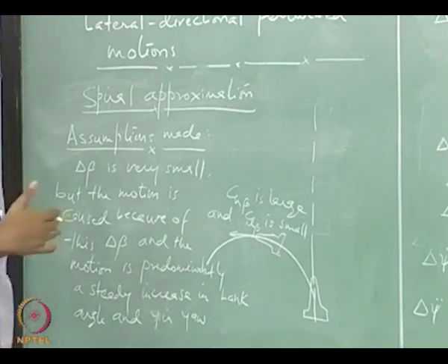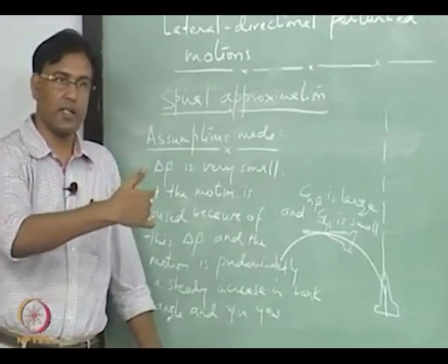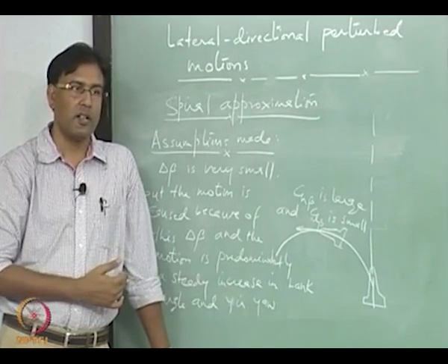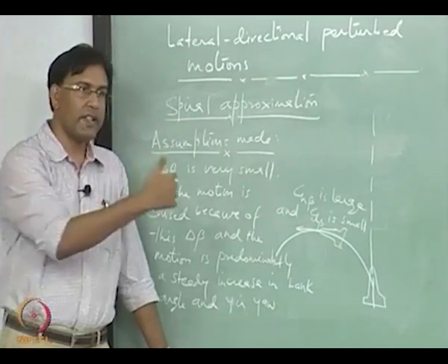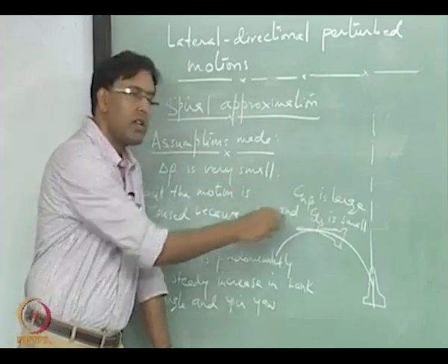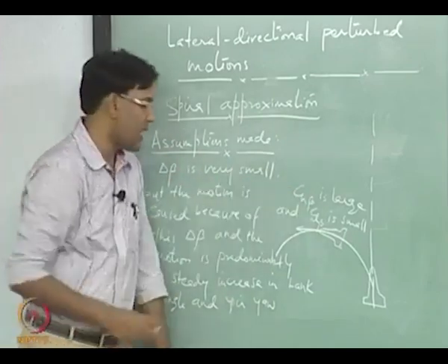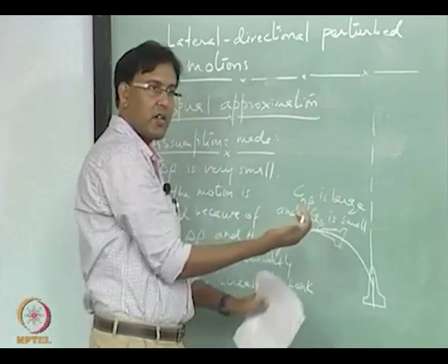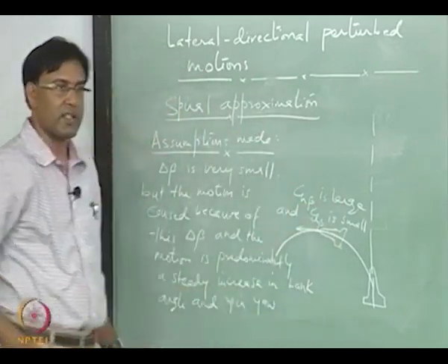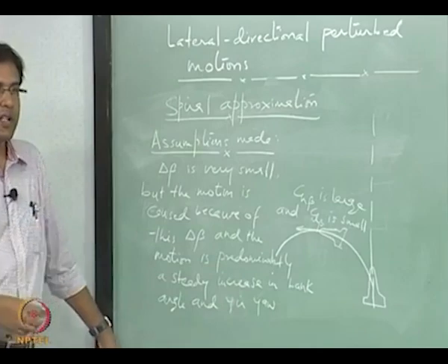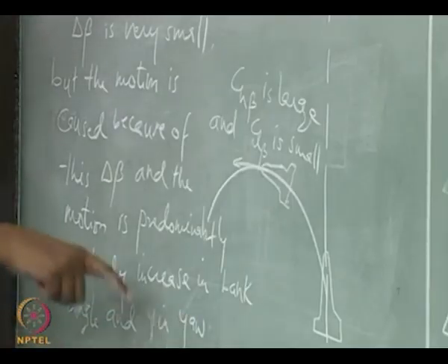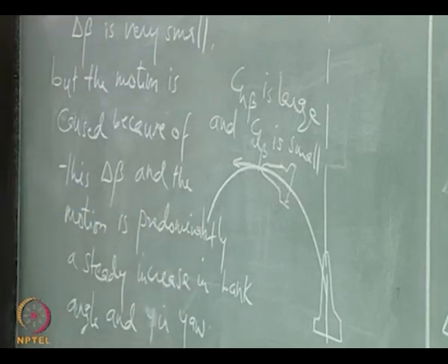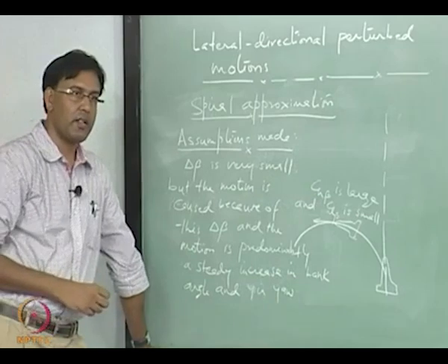Right? Aircraft is yawing, is taking a turn, so yaw is involved, right? Even though side slip is very small or is getting reduced because of this large Cn beta, it is yawing, right? We are deviating from the original direction in the xy plane, right. So, there is a yaw motion involved with a slow change in bank angle, and that is coming from this delta beta, right.